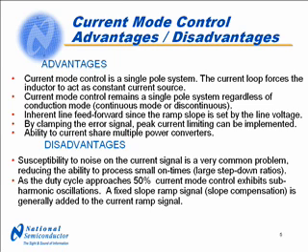Since the ramp slope is set by the input voltage, changes to the input voltage are immediately represented in the current waveform. By clamping the error signal, peak current limiting can be implemented. And it also has the ability to easily share current among multiple power converters.